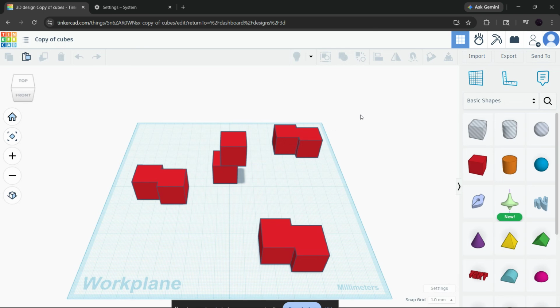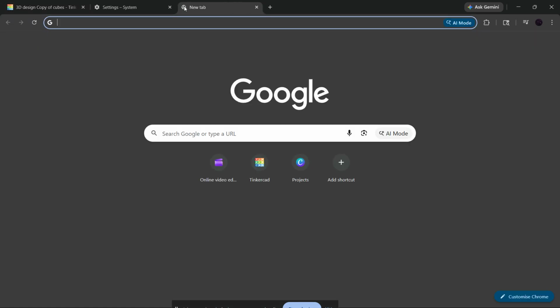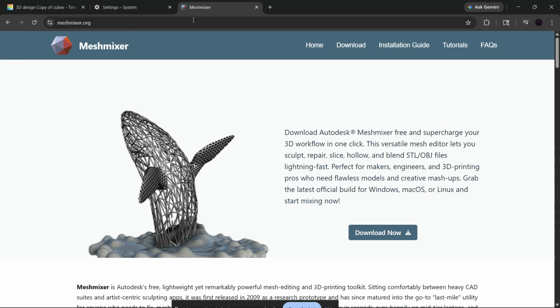If you use Fusion 360, open the file and go to the Mesh tab. From there, choose Modify, then Reduce. Your goal is to lower the face count so the model becomes lighter and easier to import. As a general rule, try to get it under 50,000 faces if possible, and even lower if the model still gives you trouble. If you use Meshmixer, select the entire model with Ctrl+A, then go to Edit and choose Reduce. This can dramatically shrink the complexity of the STL without completely ruining the shape.